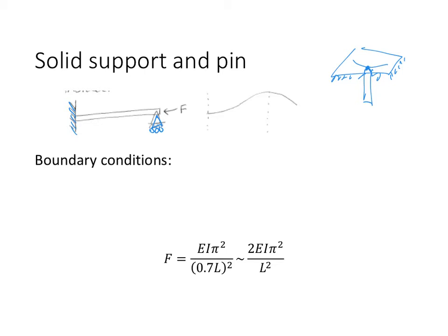It's attached, for example, maybe to a floor joist and attached through a single nail in the side that would still allow rotation so that the beam under that could then rotate into the shape that we see here, while the floor stays flat and in place and simply goes down a little bit. So we still allow the movement this way.